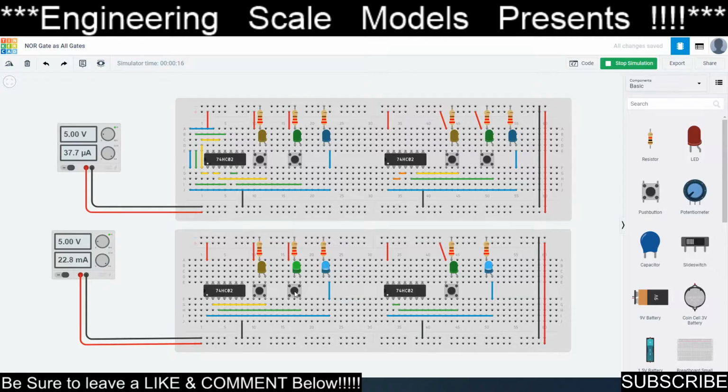If I make either one of these high, the output goes low, so that's a NOR gate. And if I click them both on, there you go. In this instance, I made an inverter, so the input is low, so the output's high, and there is that.